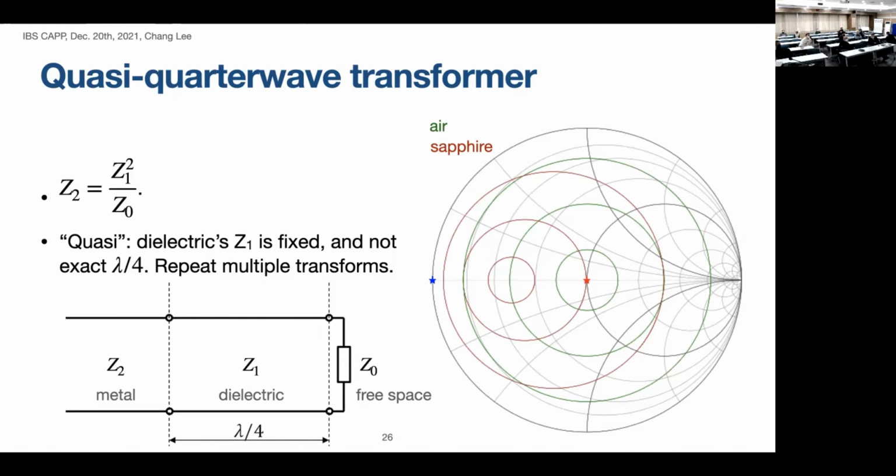Okay, so this is it. In terms of the Smith chart, for the hardcore people, this is the Smith chart normalized against the standard free space impedance. The red star is the free space impedance, and the blue star is simply a short or metallic area. The green circle is the standing wave circle, with gamma equals 0.3, 0.5, and 0.7 circles. This just means if you keep adding air distance, you just move around this one. So nothing interesting happens when you just move around the green circle. However, if you